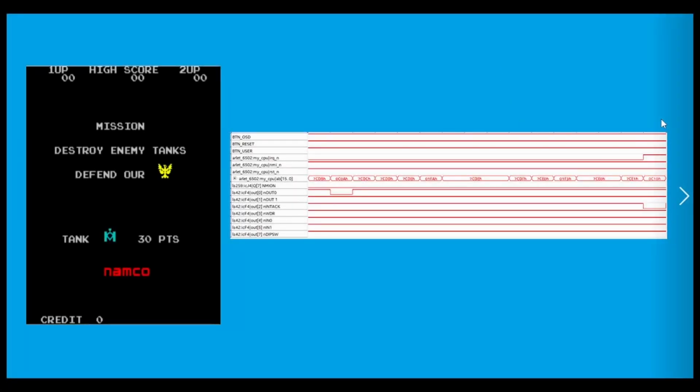The second plot below shows the main activity of this interrupt, which is to read the coin inputs and the start buttons. The important point from this figure is to see that the CPU sends an interrupt acknowledge signal that resets the interrupt on a hardware level, so the functions can be resumed.